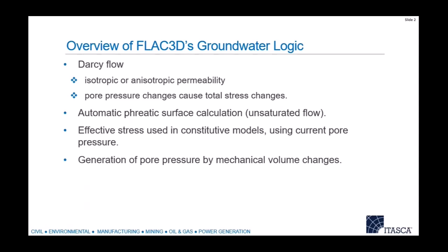Okay. So by default, we get the full phreatic surface calculation. So if the pore pressures try to go negative, they won't. They'll just desaturate pores instead, and you'll create a phreatic surface. All our constitutive models use effective stress.